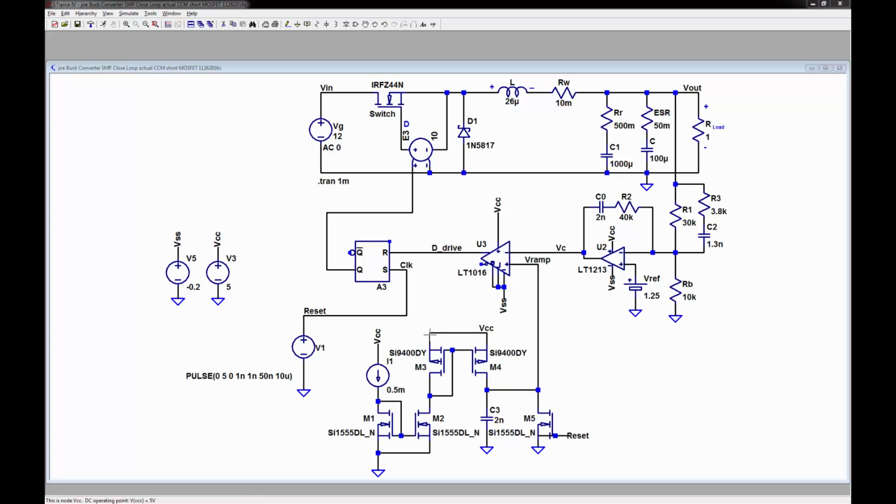Therefore, that sets up another, instead of VGS, it's VSG, because you're going from source to gate. And that sets up the same VSG here. This is a PMOS, this is a PMOS, they're the same. You match this pair, and you can buy these as matched pairs. That's what you definitely want. You want these to be matched, and you want these to be matched.